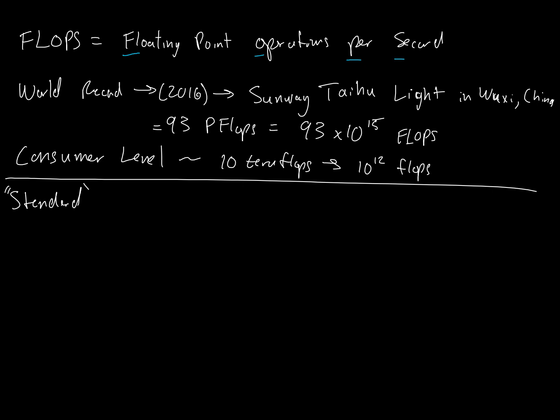So the standard simulation, which is what we talked about on the last page, will take about 1 second on a supercomputer. Now, I'm glossing over a lot of details here. When you're talking about supercomputers, the only way they can get up to this high of calculations is by putting a lot of processors in parallel, and there's a penalty for parallelizing your simulation. So you don't scale one-to-one. If I double the number of processors, I don't cut my time in half. So we're skipping over a lot of detail.